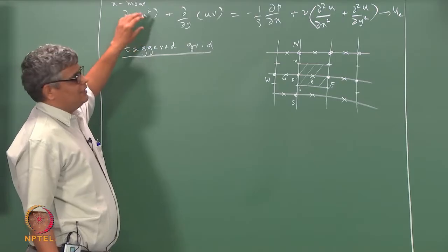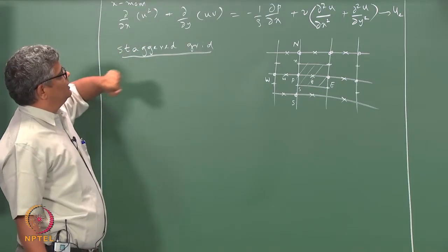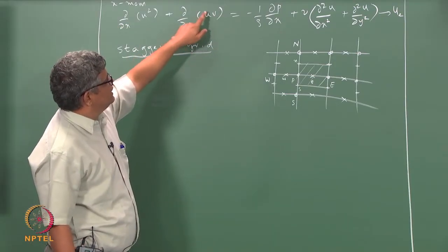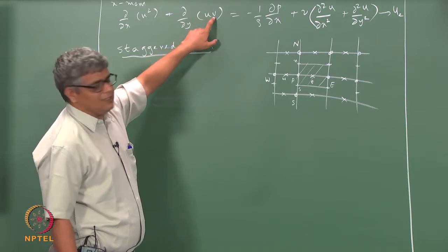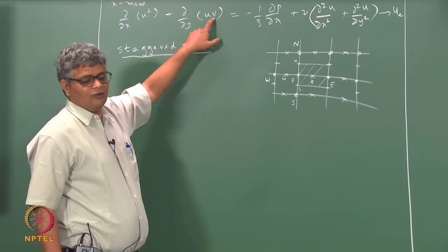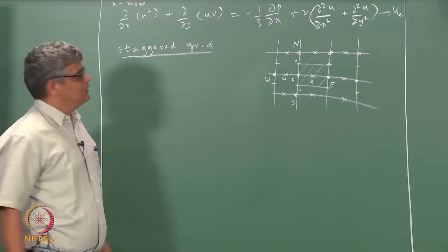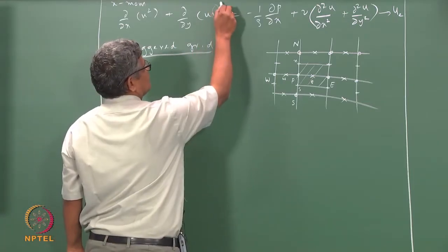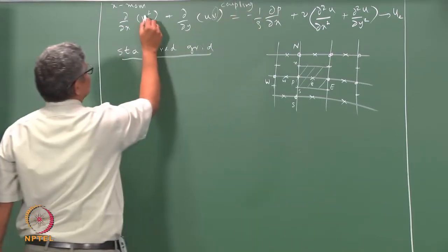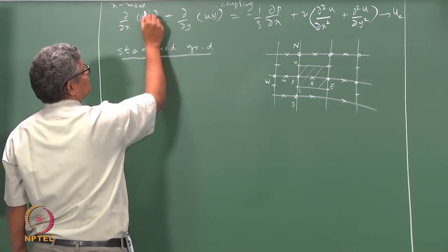Normally we have a constant times u, and here in solving this we are trying to get u, and v is supposed to be a coefficient, and we do not know the value of this coefficient v. It comes from the solution of the y momentum equation. So, this constitutes coupling, and this, which we can write as u times u, constitutes nonlinearity.